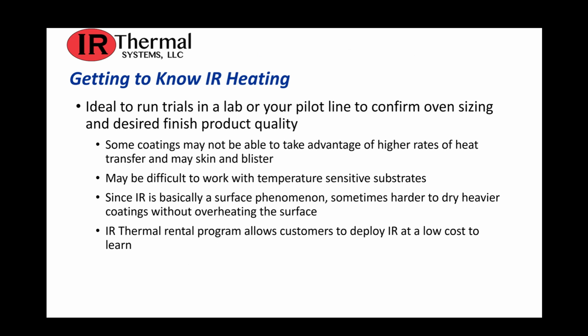So let's end the presentation by talking about how to get to know IR heating. It's ideal to run trials in a lab or your pilot line to confirm oven sizing and desired finished product quality. Sometimes coatings may not be able to take advantage of higher rates of heat transfer and may skin and blister, and may be difficult to work with temperature sensitive substrates. And since infrared is basically a surface phenomenon, sometimes it's harder to dry heavier coatings without overheating the surface. And we include a rental program that allows customers to deploy infrared at a low cost to learn.